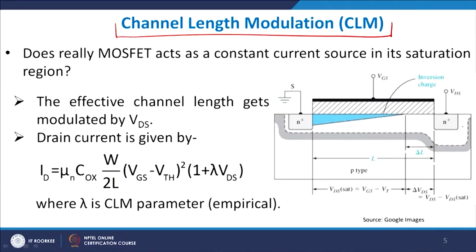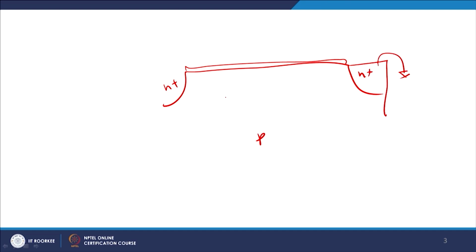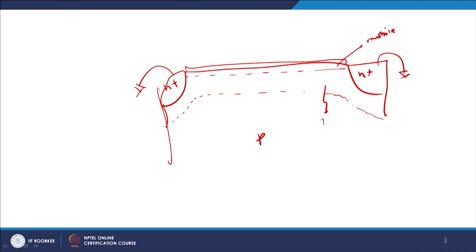Now, on the drain bias, if you do not give any voltage, then the depletion region on the substrate, near the channel, this is n plus and this is p. If you do not give any bias, this is grounded, this is also grounded, then the depletion thickness will look something like this, symmetrical in dimensions. Now, if you go on increasing it, time will come when you will have an inverted layer here. So, this will be mobile charge carriers, and you will have fixed charge carriers here. Again, we have still grounded our drain.